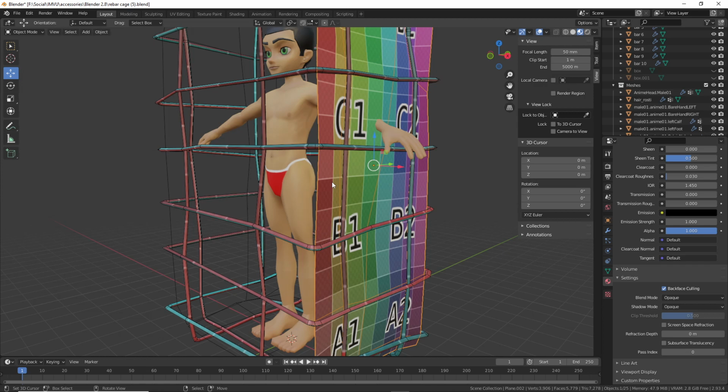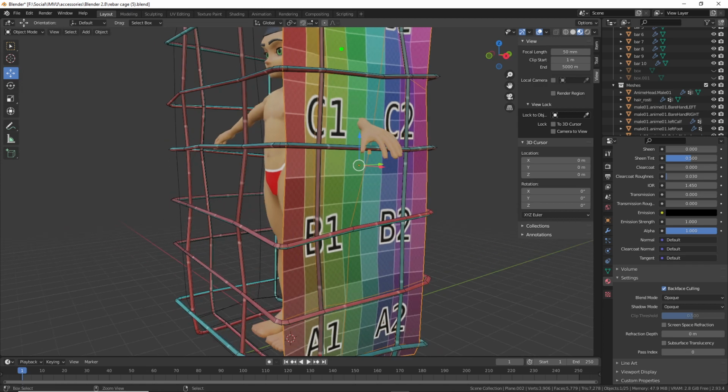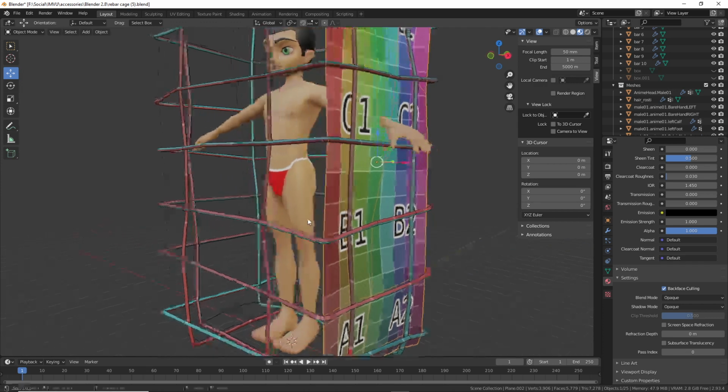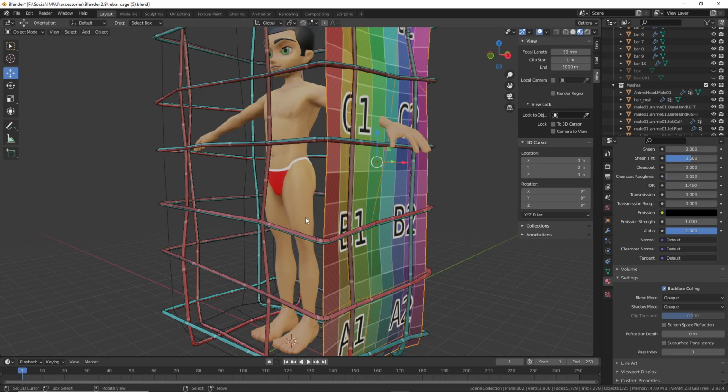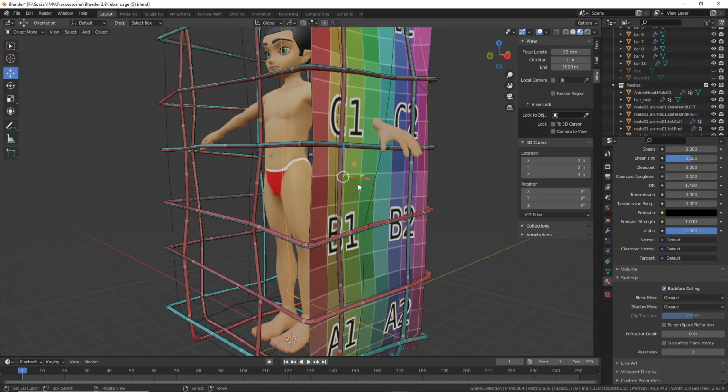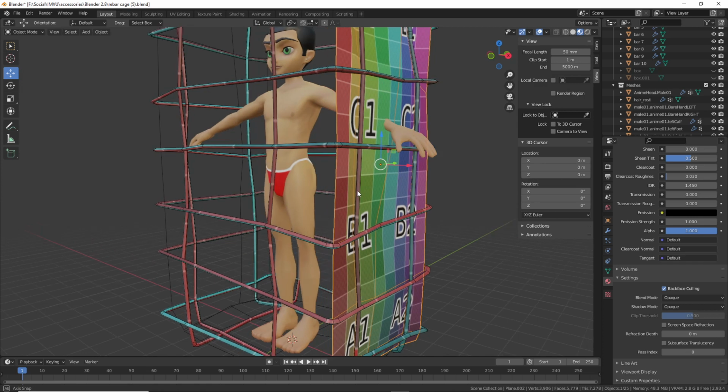We're going to make a grid texture for this, like that. The way that IMVU does its double-sided thing normally is it literally just duplicates the faces. They point outwards by default, and it duplicates them and points them inwards.